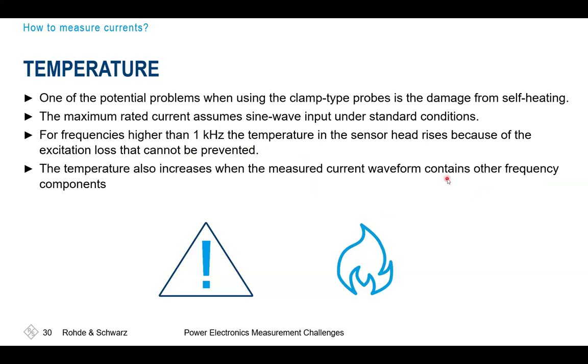So please be aware of these derating curves and check upfront what frequency range will most likely be induced, by checking the maximum slew rates as well as the switching frequencies inside your system.